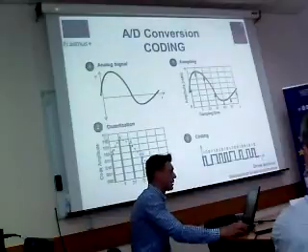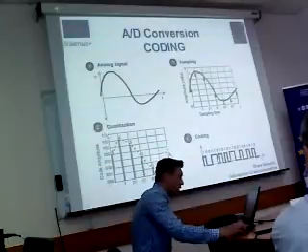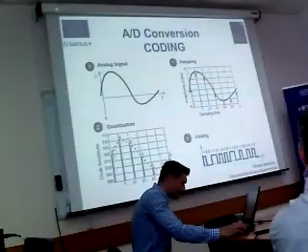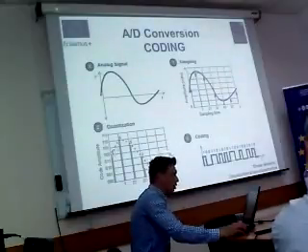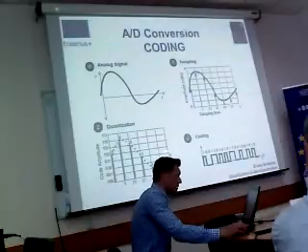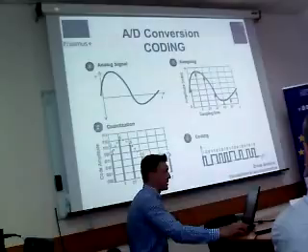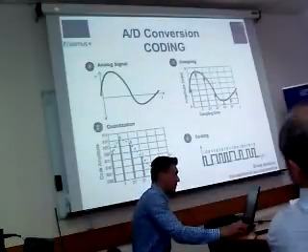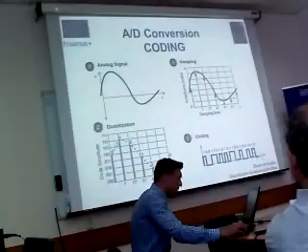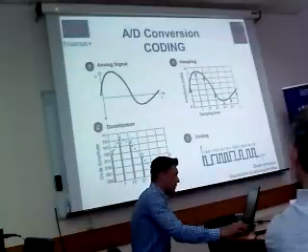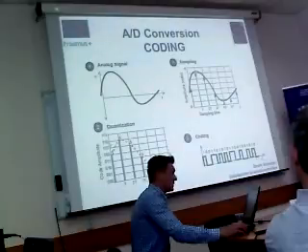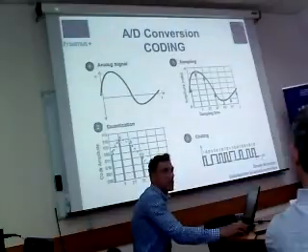So when we decided that our analog digital converter is only 3 bits, we've got only 8 recognizable levels. So each of the probes has to be moved to one of these levels. And then coding is only reading the number which stays alongside this recognizable level. So if this probe fits this level, this level has a description, and the description is 110, and it's our code.